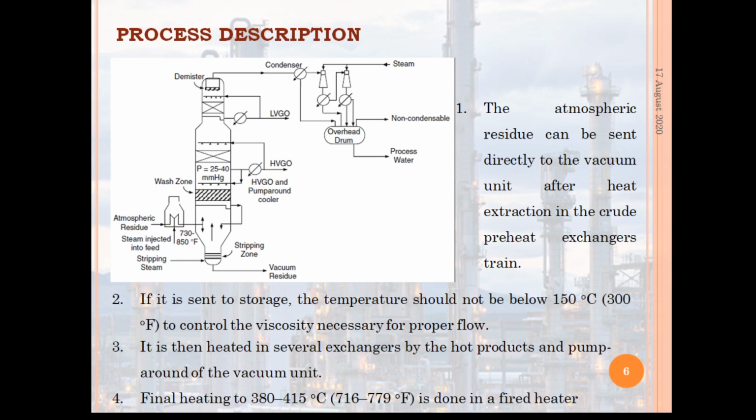Then it is heated in several heat exchangers by the hot products and the pump around of the vacuum unit. Then the final heating is 380 to 415 degrees centigrade in a fire heater.